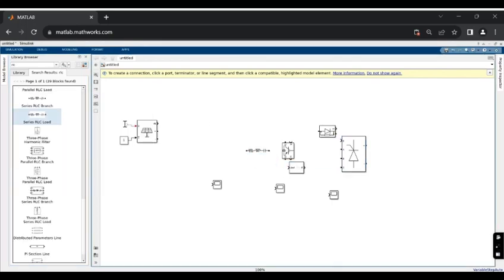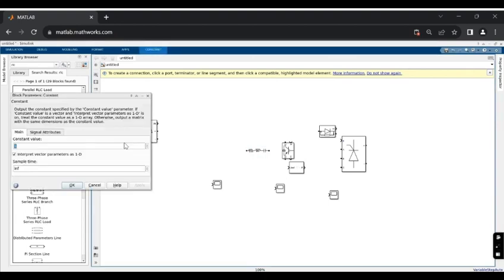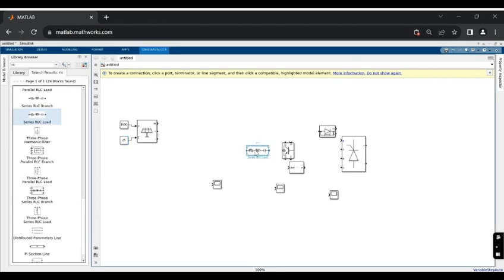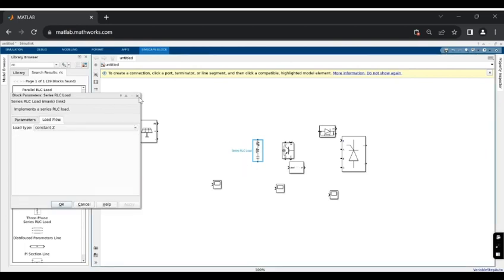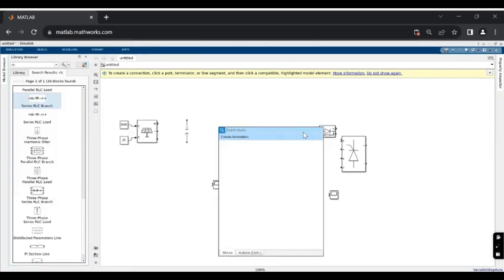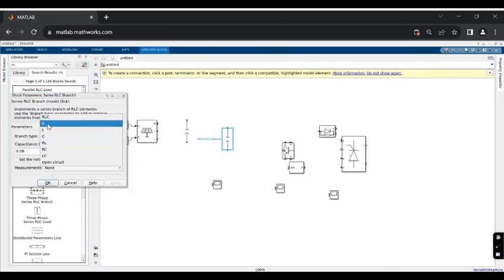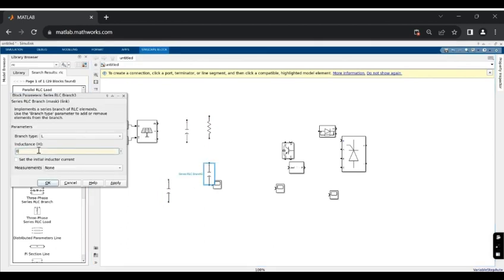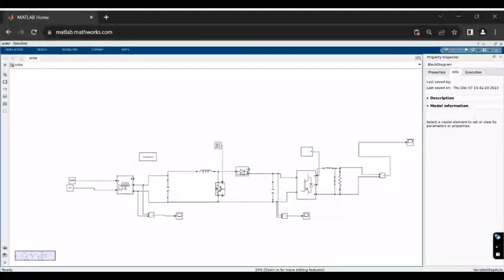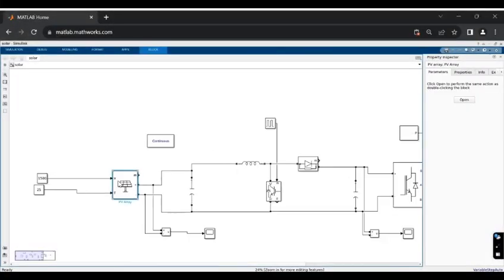The voltage measurement is connected to the scope. Now take the parallel RLC branch, changed to the capacitor, resistor and inductor as we need. Now take all the components as required, as shown in the figure: capacitors, inductors and resistor. Connect all the components as shown in the circuit.